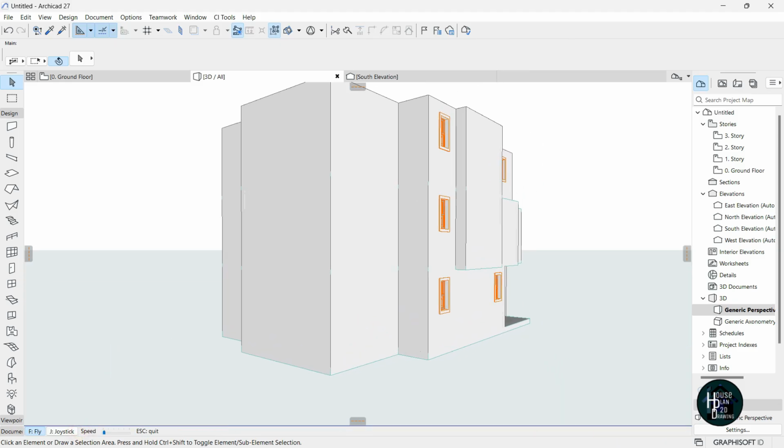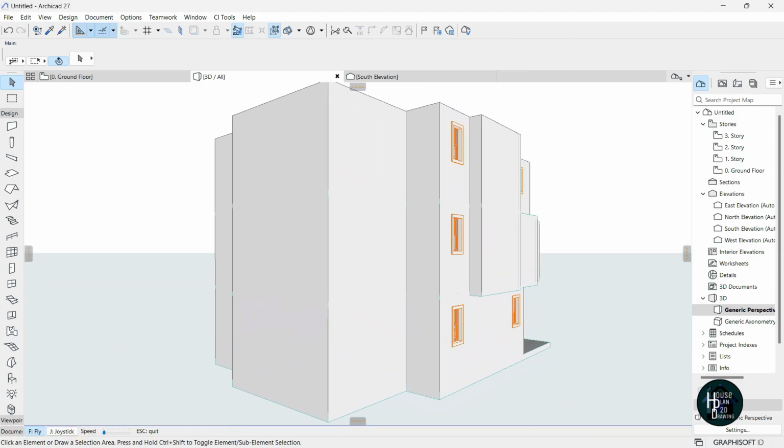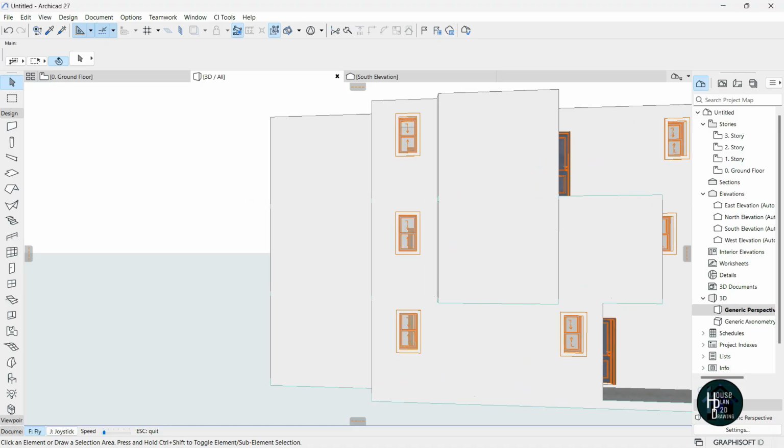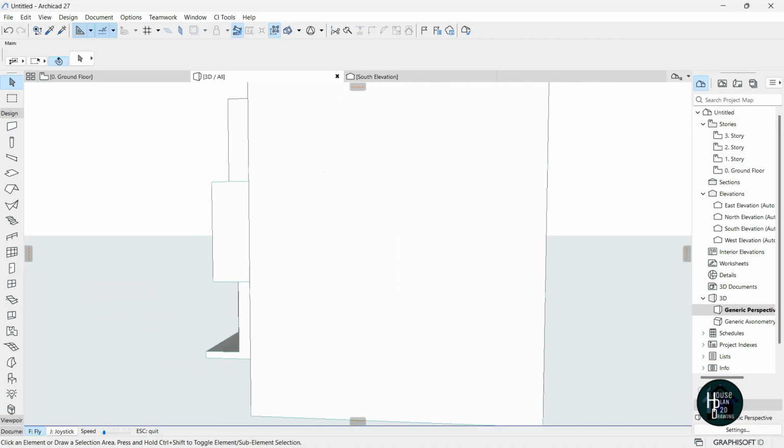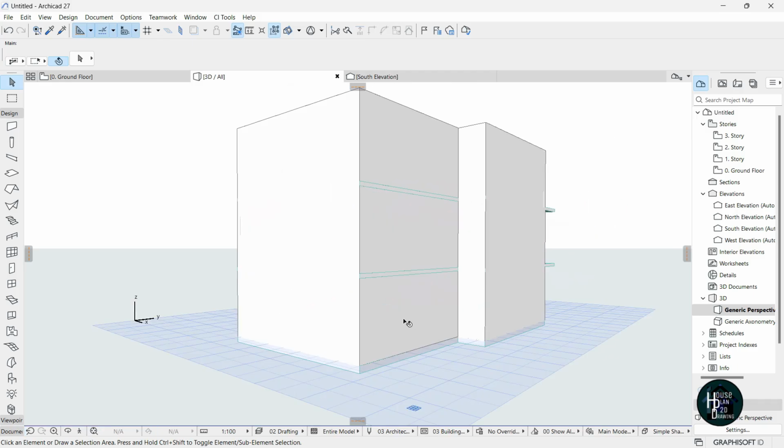So these are some of the tricks you can use to know if your walls are straight or not straight. So we've rectified that. Okay, let's go and rectify this other side here. Click on this one, just delete it. Click this also and delete it.